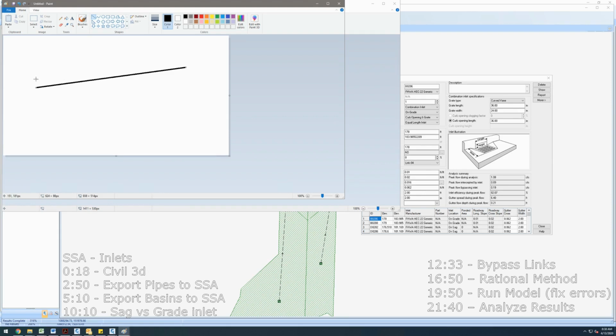here's your, say this is your gutter line. Here's your curb. Here's our inlet. And I guess I just need to draw it in. On a really steep roadway, water is going to fly really quick and hug tight to that curb line, and maybe there's going to be a little bit of water that goes around.